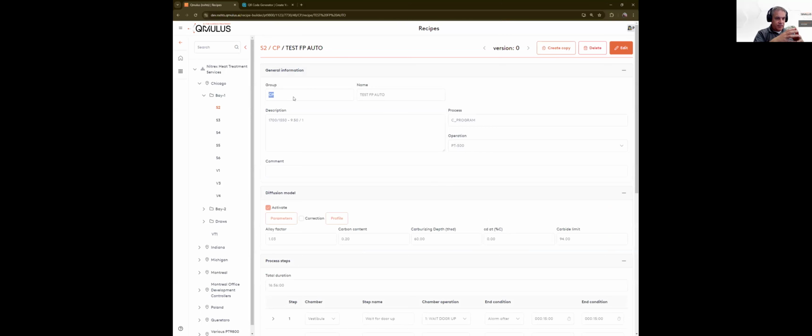If I create a recipe, say a 4-hour carburizing, and I save it in Eurotherm number 1, it's in Eurotherm number 1, and it's going to stay in Eurotherm number 1. If I go to furnace 2, I have to create another recipe. But by using this group, QMULUS is now going to share these recipes with the many Eurotherms. I use that with a trademark name there, whatever. Don't sue me.